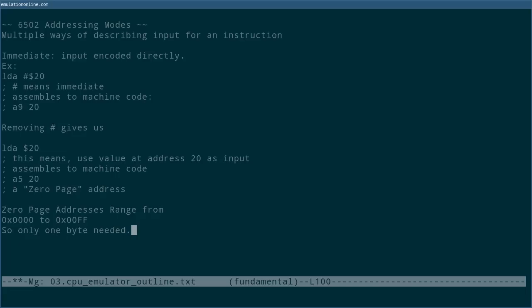When we were looking at the machine code for the earlier instructions, you may have noticed that they are very similar, A5 versus A9 for the opcode. Fortunately, this is not an accident, and is one other way that clever design has made the CPU easier to implement, both in the original hardware and for our emulator. The encoding typically uses some bits for the operation and some other bits for the addressing mode. This means that instead of implementing 128 completely different instructions, we can implement roughly 56 unique operations plus 13 addressing modes.